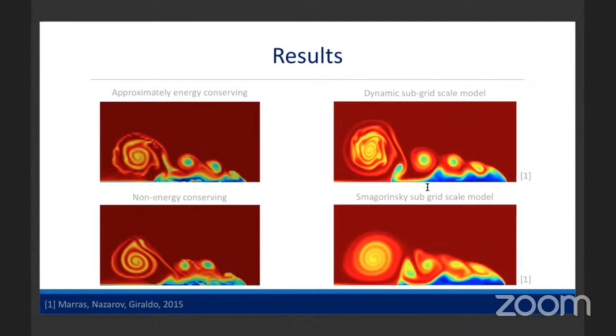The idea with subgrid scale models is that you apply a spatial filter on your equations, and then you get an additional term in your equations that corresponds to the subgrid scale. And this you can then discretize in various different ways. One of these ways is called the Smagorinsky subgrid scale model, which essentially discretizes this term according to a sort of physics-based heuristic.